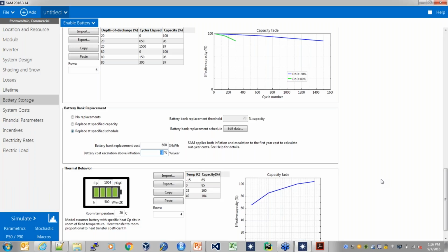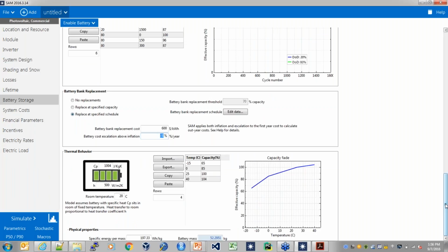We had one question on the relationship between battery capacity and operating temperature. Maybe you could revisit that. Sure. So, as many of you might know, if you leave your cell phone in your car in the garage during the winter, and you come back in the morning and it's dead, that's because battery capacity is a function of temperature. As it gets colder, battery capacity decreases. As it gets warmer, battery capacity increases. However, the degradation of the battery also increases as temperature increases.